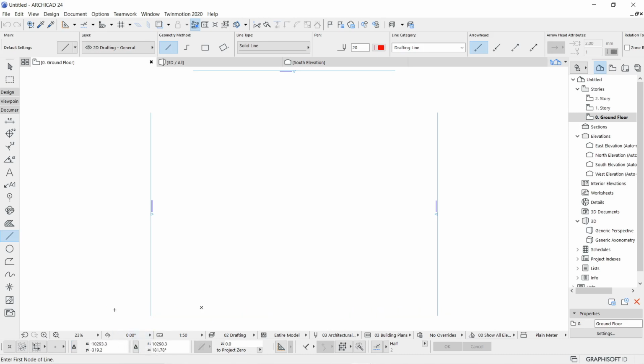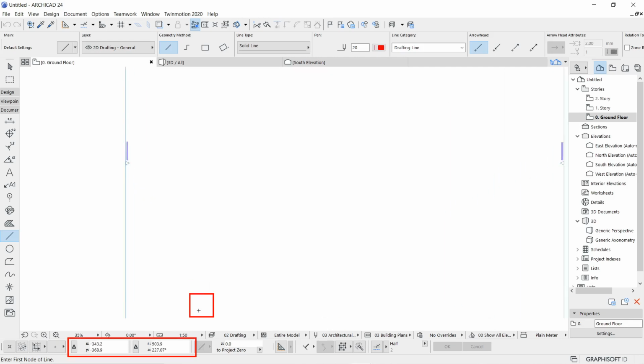Absolute is nothing but with respect to origin. Then you will ask me where is the origin from where I'm going to draw. If you just keep moving your mouse and try to touch the thick cross sign which you can see on your screen, your X and Y is right now getting displayed as 0, 0. If you want, you can slightly zoom that by using your mouse wheel button and just make the display comfortable. That cross sign won't be changing its appearance.